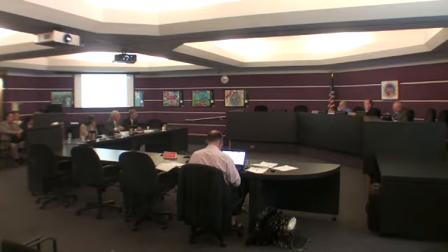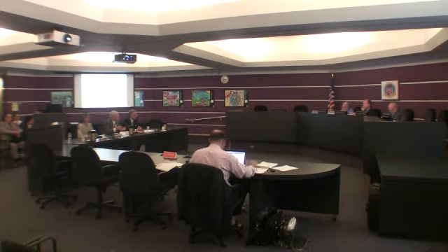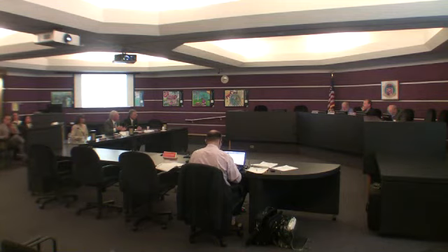Sure. My name is Gerald Strickland. I'm the Director of Nuclear Projects for Diablo Canyon. Okay. And what we expect is that as the SHAC process completes the development of seismic source characterizations, then associated ground motion characterizations, that will then be used as part of the response to the Nuclear Regulatory Commission's Orders 50.54(f) to be able to then create a new seismic spectra for Diablo Canyon, compare it to the existing design bases, and in turn evaluate whether or not there are additional studies that need to be performed to assess the capabilities of the plant. An example would be that if, say, on the low frequency end of a spectra, you determined that you had some responses outside the range of your current spectra, you go back and you look at what types of equipment, components, systems would be sensitive to that type of motion, and in turn then evaluate as to whether or not any additional motion would have an impact on the qualification of those components.